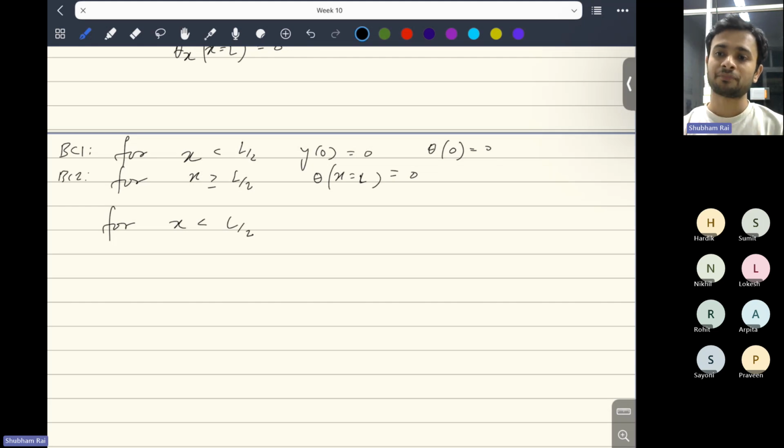Whereas if you write the force balance, it will simply be that if you have a shear force along the positive y direction, it will be positive, and if you have a shear force along the negative y direction, it will be negative. There will not be any role of face, any face. Okay, so only in the calculation of stresses do the faces come in, because stress is a tensor. It contains the information of face normals.